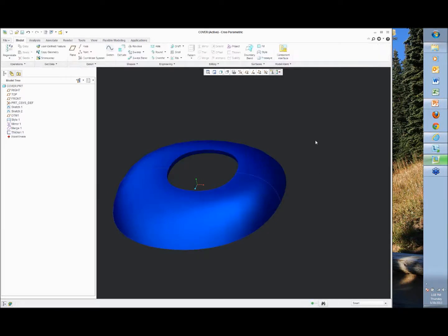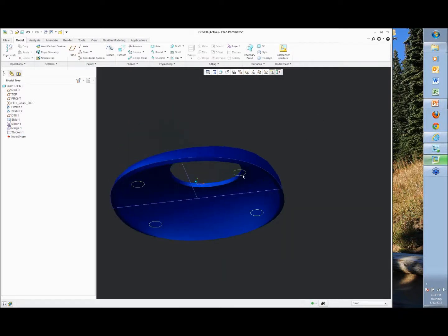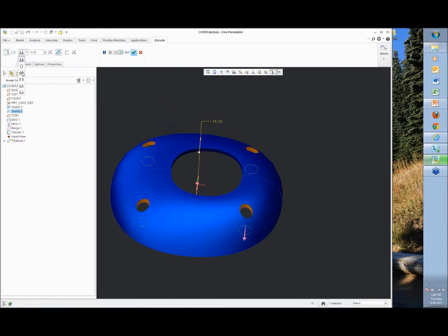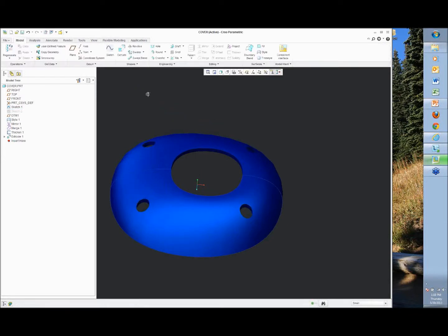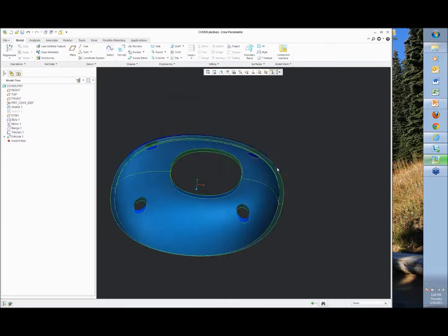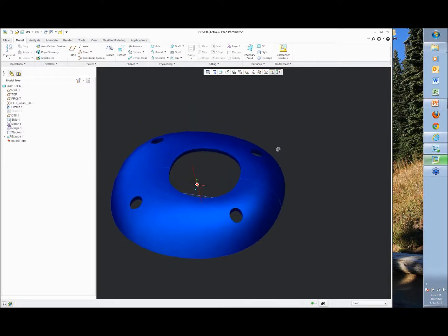There's my solid. I told you I put in this original sketch here to set up my holes. Maybe this thing has to fit over those holes. So because it's a solid, I can do the extrude tool, remove material through all. Done. So now this cover I know will fit over the top of whatever those posts were. And it'll allow me to manipulate this a little bit.